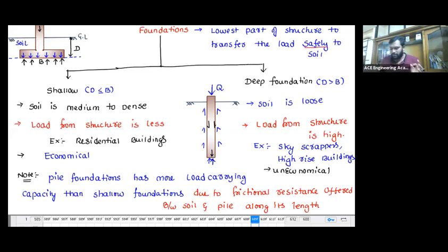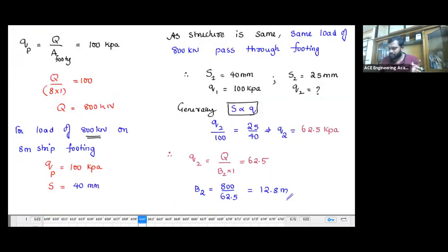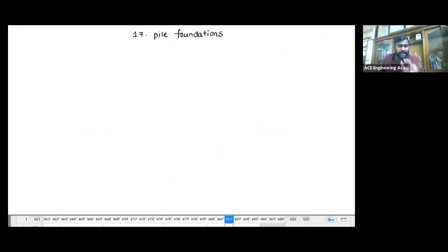These points I have all discussed here. Now let's see it in a simple point. First we check with raft. If the raft is not able to transfer the load safely, then you go for pile foundation.